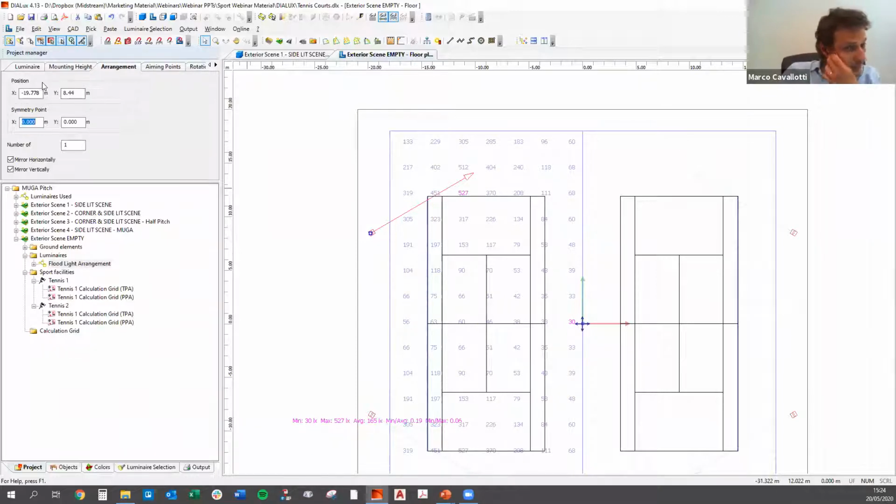And by using this position tool, you can also set the position of the pole, because these represent a pole. For this purpose, we want to have it at 12 meters for the y-axis, which is the end of the PPA, and just as an example, maybe 20.5 meters for the x-axis. So this is 20.5 and this is 12 meters.